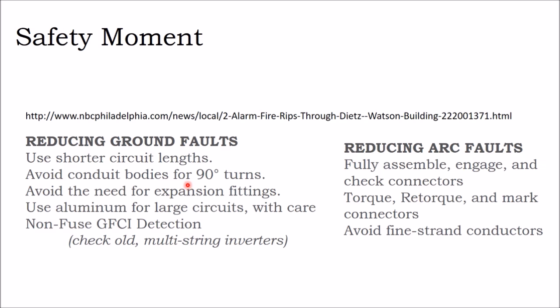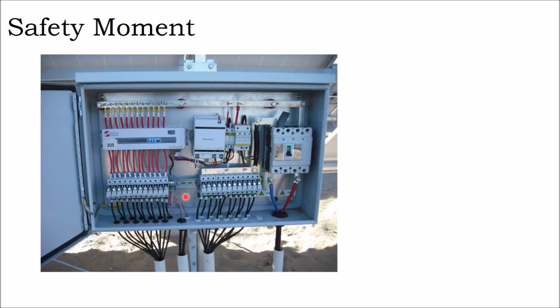And so some of the lessons learned about ground faults, and the problem is with old school kinds of inverters, they would read the reference voltage to ground of the inverter and its ground fault detection system. They would take the negative reference and attach it to ground and say, what's the difference between the two, and any difference would trigger the ground fault detection.